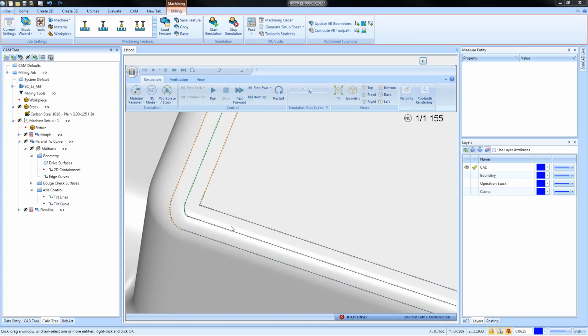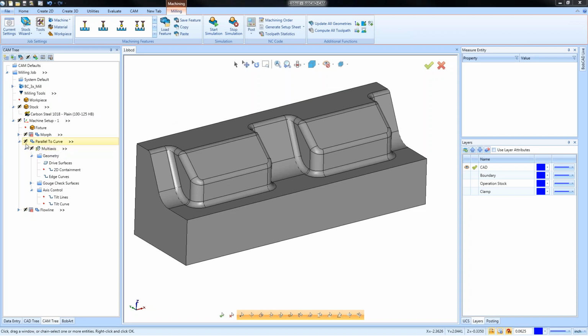If you want the best quality surface, depending on the machine you're running, some machines want less movement, some machines want more movements. So depending on your machine, you can start controlling that point distribution, or the way those entities are broken up, to feed your machine what it wants in order to get superior finishes. And really that's what it's all about, is getting superior finishes, right? So point distribution, you're going to find this in, I believe, all of the surface-based toolpaths here.